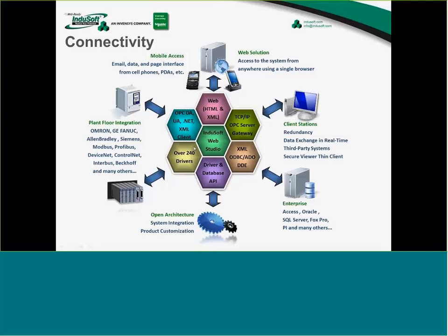So, for example, if you have a 1500 tag license that supports 3 drivers, you could communicate to 3 different PLC networks as well as an OPC server in addition, all simultaneously. And again, share information between OPC and drivers, or drivers to OPC.